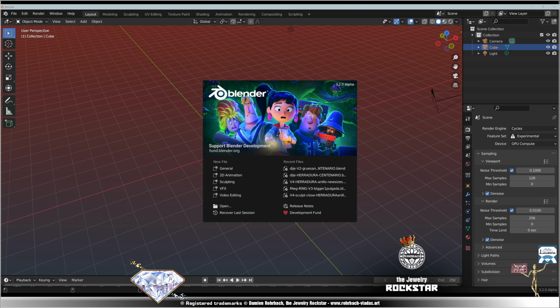Okay, so we want the distances to be pretty even here and there, and also we need to check those thicknesses. So add mesh, let's add a sphere, and let's come around here and have a look. Okay, here we have around 0.5 millimeters. All right, this is the lower limit. You don't want the lower limit.